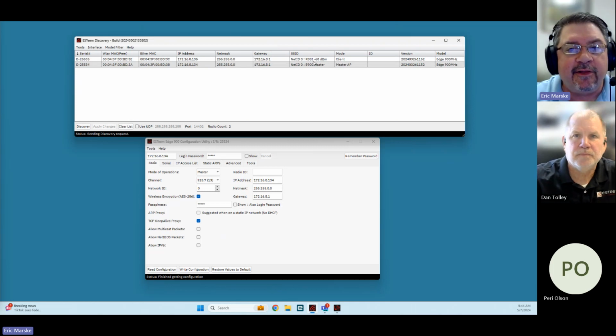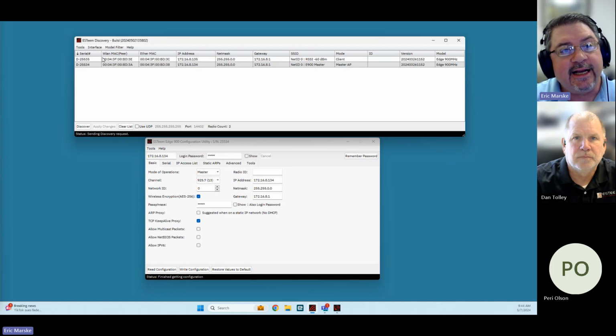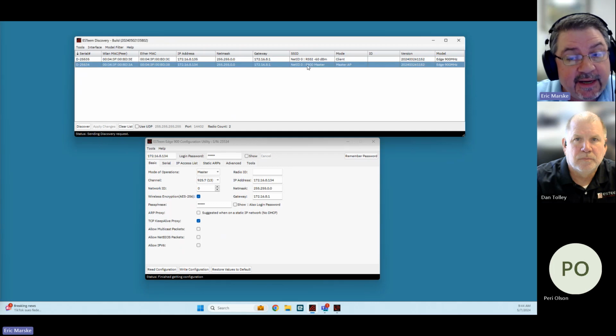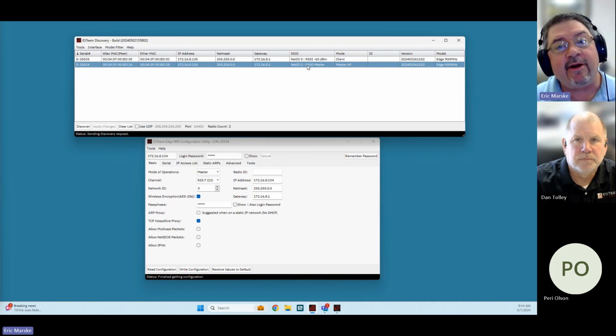we'll see on here that the received signal strength for that remote radio is actually listed within the Discovery. So if you've got 5 different remote radios, each of their signal strengths will be listed there. The only one that isn't listed is going to be the master site itself. But every network can only have one master. Every other radio outside of that will be a remote. So the signal strength is going to be the same coming and going from that master site.